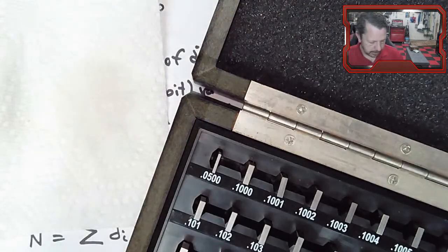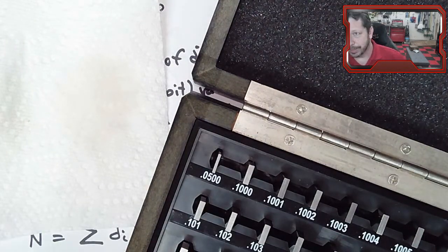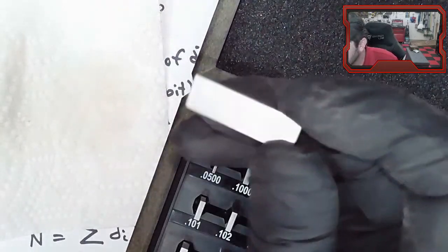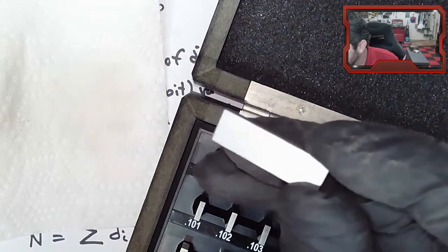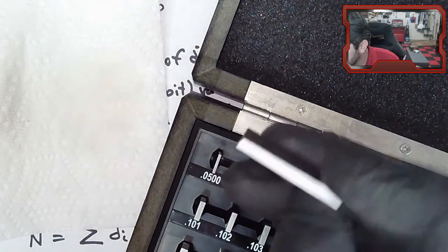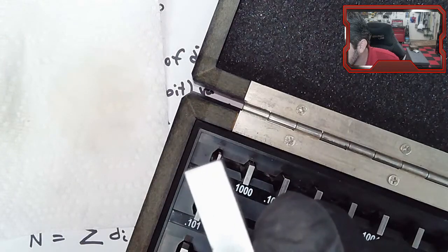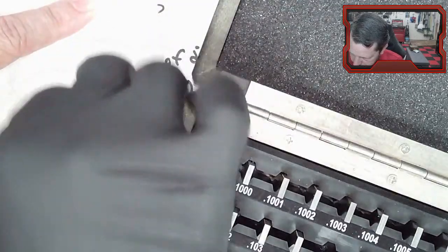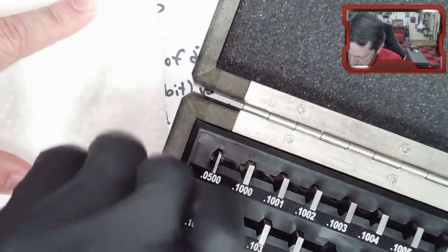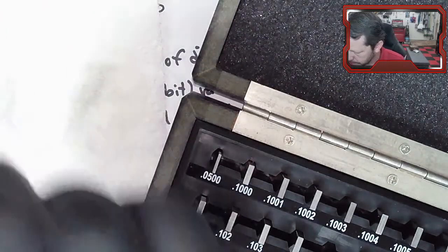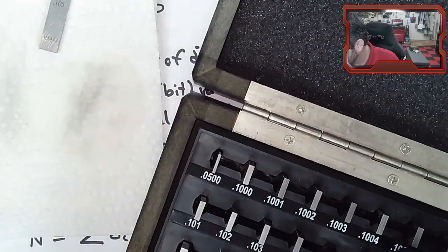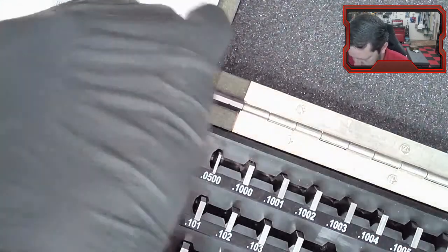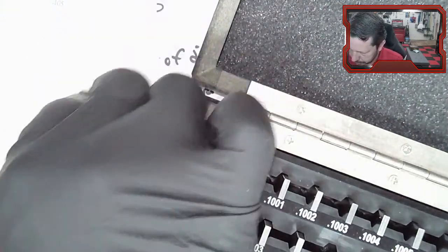There are some other processes, like my gauge blocks could probably benefit from being flattened a little more. In fact, you can kind of see, or I can see, I don't know how well you can see, that this surface should be really polished. And so should this one, but I can definitely see the scratches on it. But you clean them a little bit on each side, particularly the side that you want to wring together. So I've got a 0.15, and let's get a 0.18. Was that the really bad one? No, it's actually really pretty good. So I'm just cleaning the side.